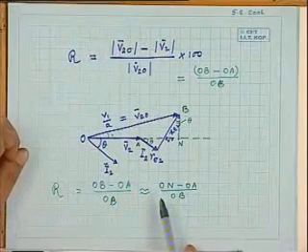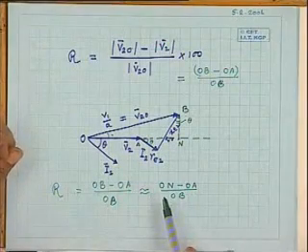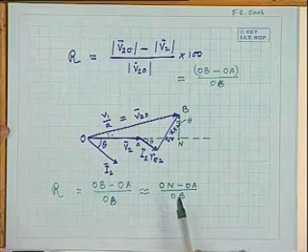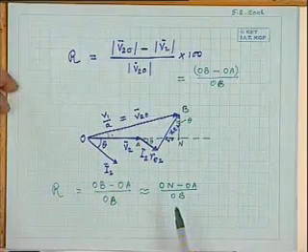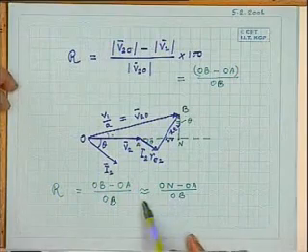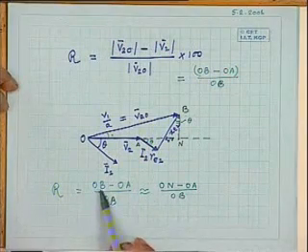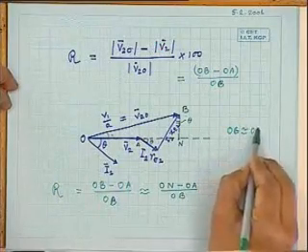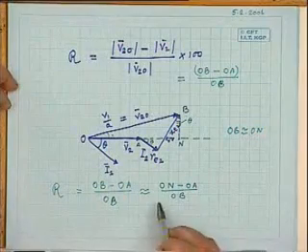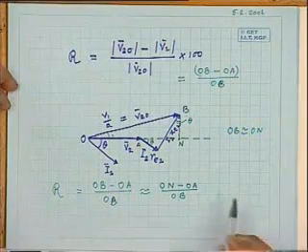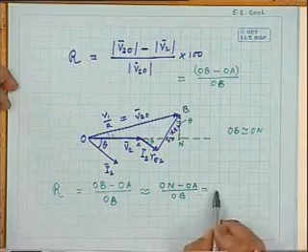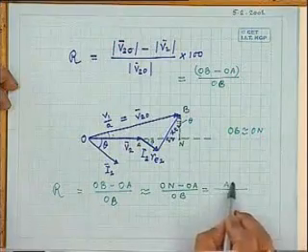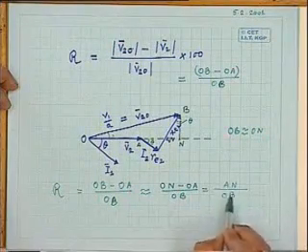And this we are allowed to do because of what? Because the resistance and leakage reactance voltage drops are small in a well-designed transformer. So that allows me to approximate OB as ON. So we get this one. Then obviously this ON minus OA is nothing but your AN divided by OB.